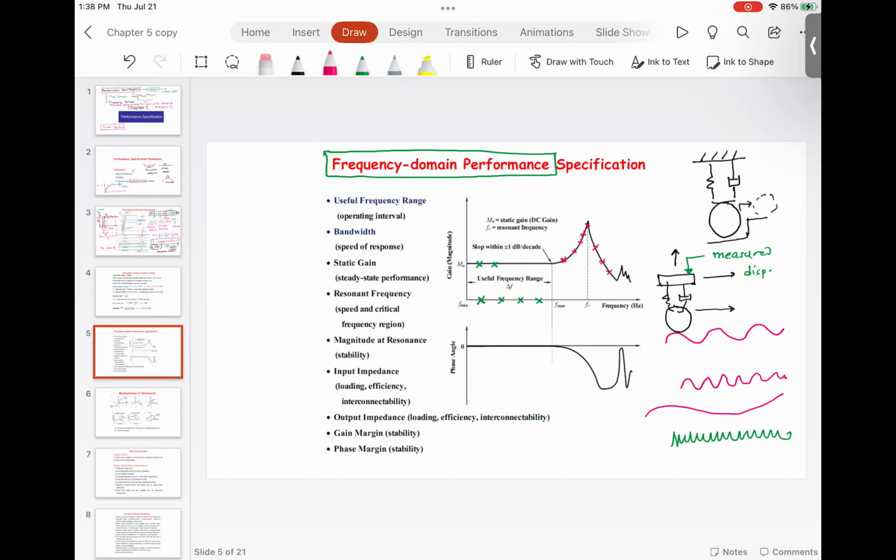The classic example that I talked about in the last class is the washer. If you have the washer set on the spin cycle, at certain low spin speeds, the washer does not vibrate. As the speed increases, the washer starts vibrating. At critical speed, the washer vibrates violently and perhaps walks away.